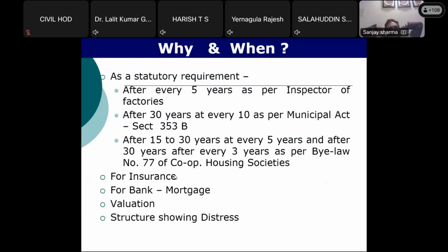Even in Chandigarh, all the CBSE affiliated schools have to get a structure stability certificate. Because they don't have systems installed to monitor the behavior of structures, we do non-destructive testing there, go and see, and carry out present strength assessment.